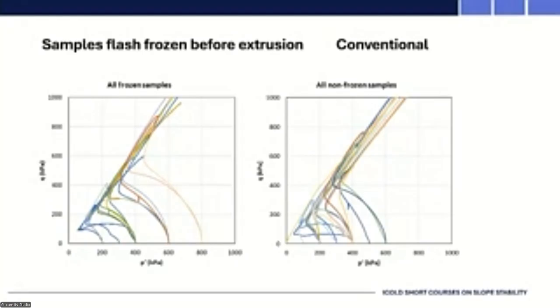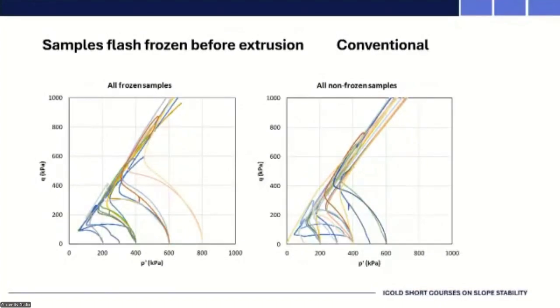So we did not see a single sample that contracted. Does that mean that the soil does not contract? It certainly does not, because the samples that dropped out could not be tested. And I think they are the samples that we are really interested in. So our nemesis and our serious challenge is still how to get those materials out of the ground to be able to test those. So the benefit of having a mobile lab is secondary to this.